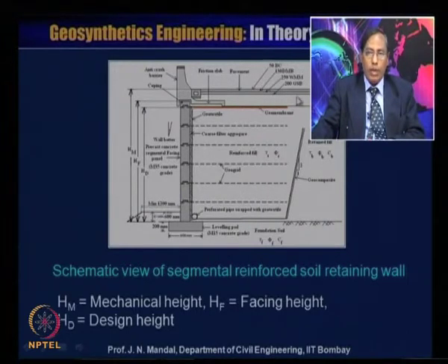You can provide sometimes here also the addition of GeoGrid reinforcement, which can reduce the thickness of the pavement, and you require a proper kind of crash barrier, because sometimes when there is an accident, the car can hit this barrier, so it can be prevented. So this also requires a proper kind of design, though sometimes it is related to structural analysis, but